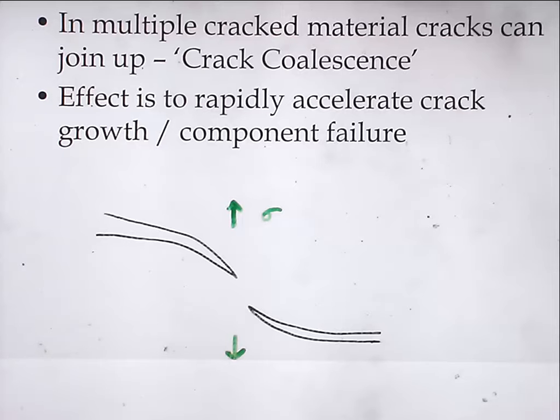So this is ductile failure, okay? Classic ductile, yeah? And all you've got is what they call microvoid coalescence. You've got a little honeycomb network of ductile overload.